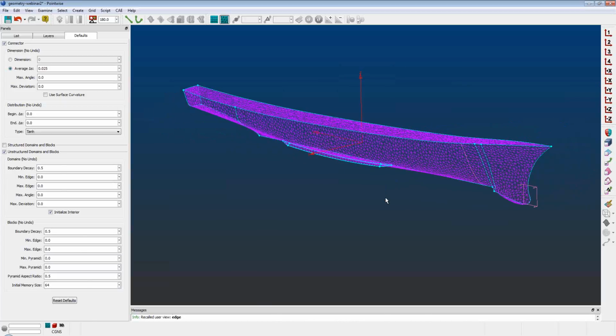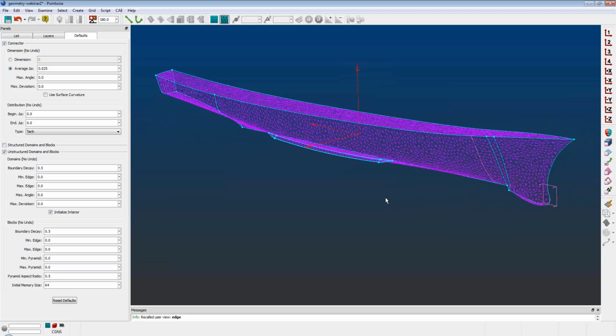First one is, after you apply the geometry healing and filling the gaps, those types of operations, are you still able to subtract new volumes or new surfaces from the modified or healed geometries? Do you have any troubles with that? Many of the commercial softwares don't really allow the split or subtract operations. Yeah, there shouldn't be any problem. This is a little bit similar to the question that Maxwell Starr just asked, where if I have multiple surfaces in this model, can I cut a hole or can I trim across multiple surfaces? That's perfectly fine, because most of these operations are done on the model level, and they work optimally on the model level. Okay, great.